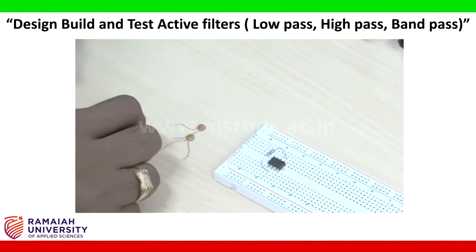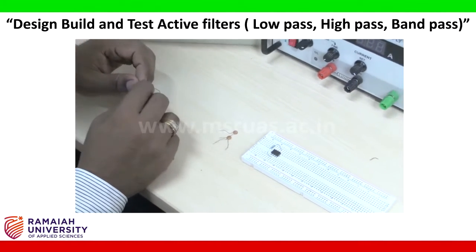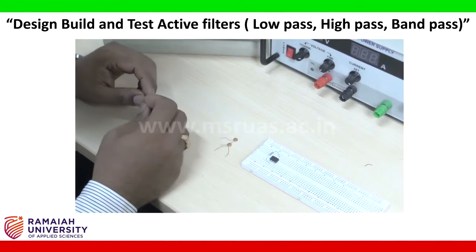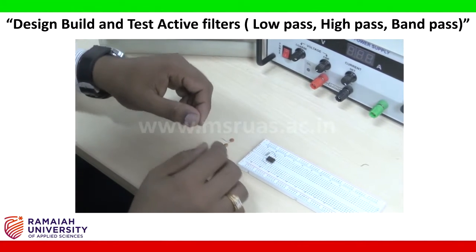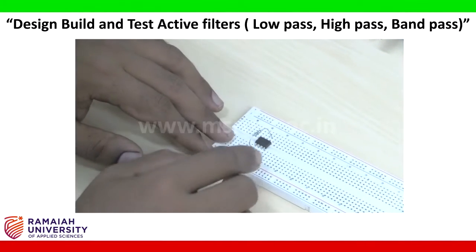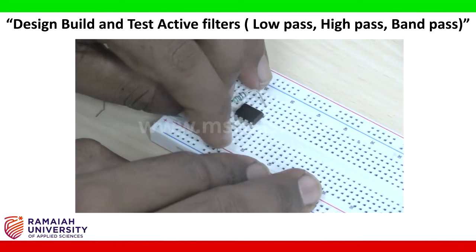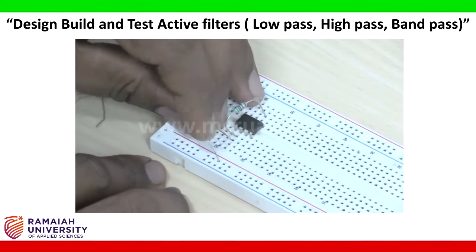Now I am going to connect the 10 kilo ohm resistor to pin number 2 to ground. So the 10 kilo ohm resistor will be connected to pin number 2, and pin number 2 to the ground I connected. So this is the ground connection.